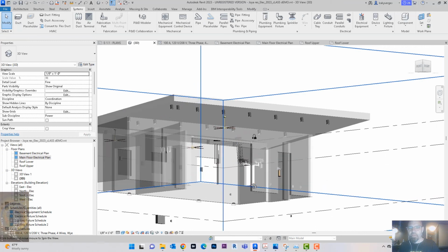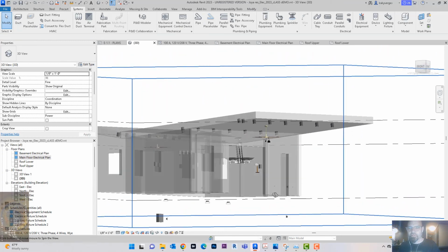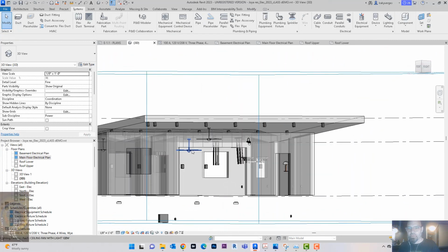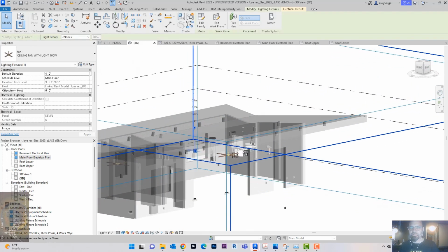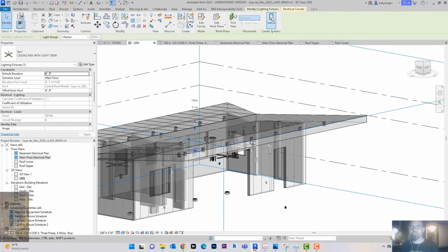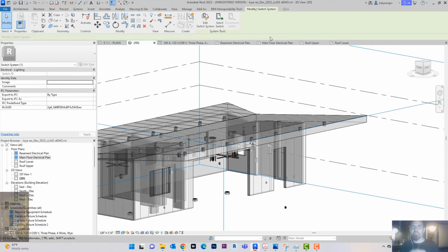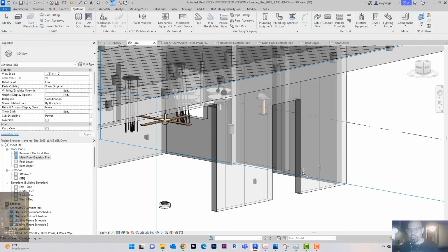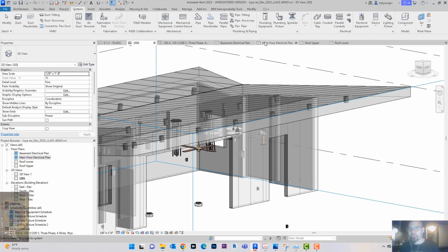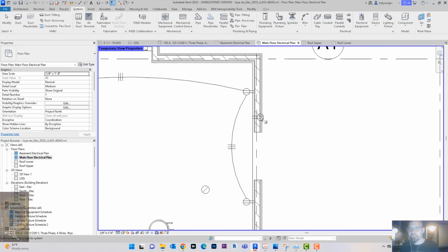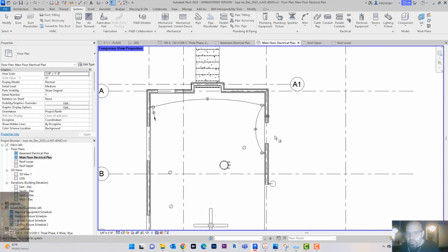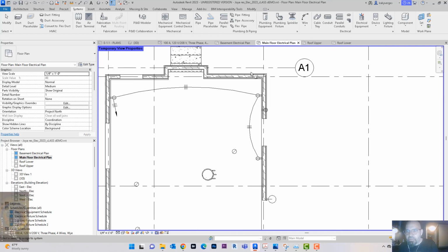We're going to grab a light fixture. So let's grab this fan here. Okay, see where it says switch up here? So I'm going to click switch. And what that is doing, so it'll say select a switch. And I'm trying to find that switch here. Where did I put that switch? And of course I can't find the switch.